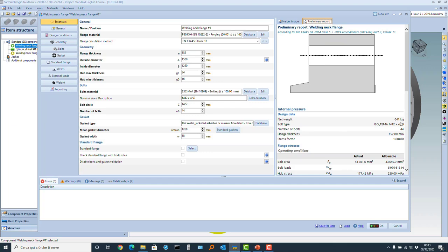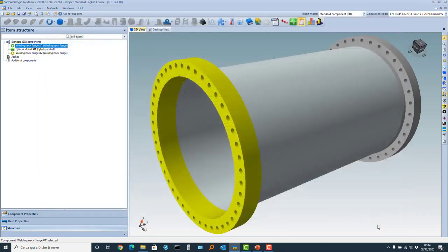So we have taken out 90 kilograms from the finished weight. That means something more from the weight of the starting ring. However, please take into account that one of the big difference was the fact of using a hydraulic tensioner instead of an impact wrench. So we have used a device with a better control of the load, with less scatter value.